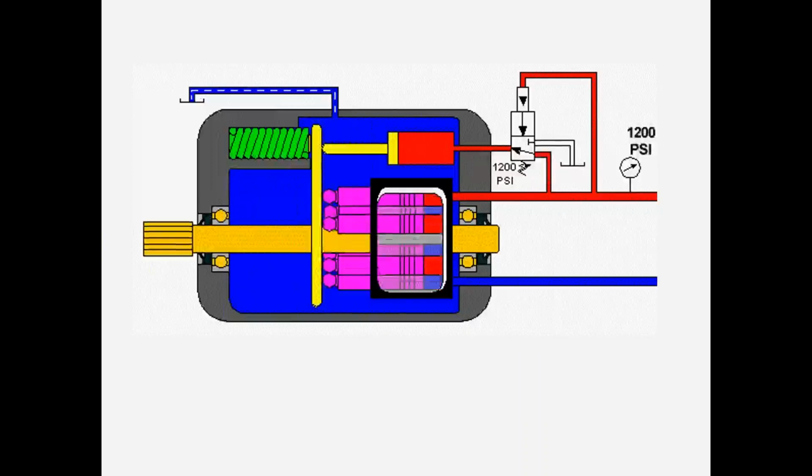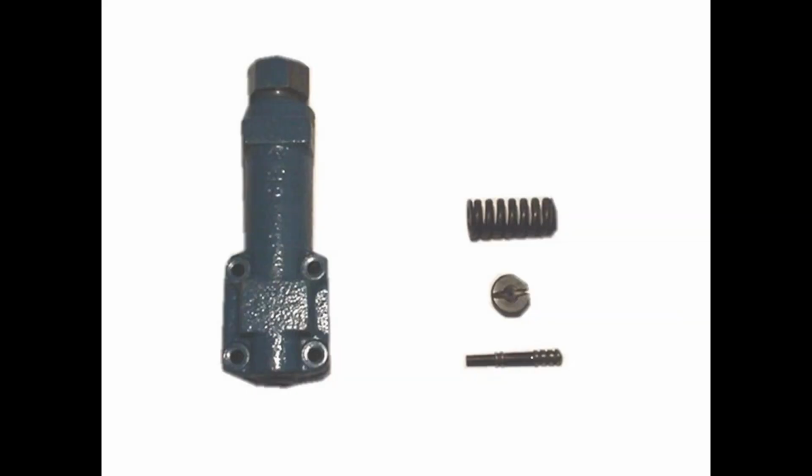The pump is going to do this. Right now, it's also possible for it to stick the other way, where the pump stays at full stroke all the time too. But this is most likely to happen, is that we'll get plugged up over here, and the pump will be stuck in a position where it can't stroke.